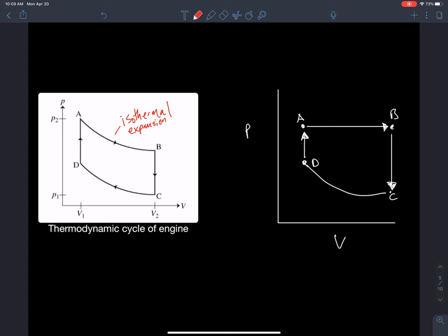So that's some type of venting situation that's occurring. And what type of transition is that? If it's not changing volume, that is an isochoric transition. Okay, and as the system is going back on another isotherm, that would be an isothermal contraction, or a compression, isothermal compression or a contraction. And then from here, the system is gaining heat rapidly, all right, without changing its volume. So maybe some type of ignition happened inside of the piston to go from one pressure to the other pressure, and that is an isochoric process.